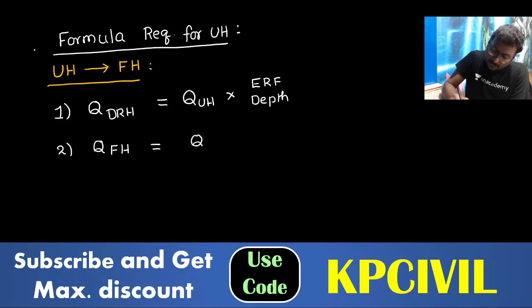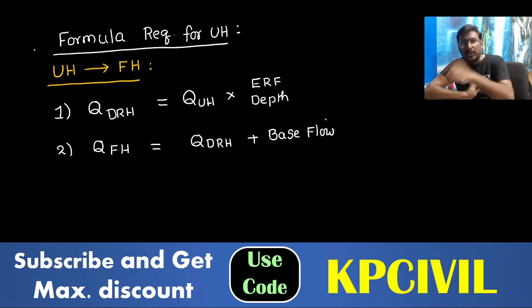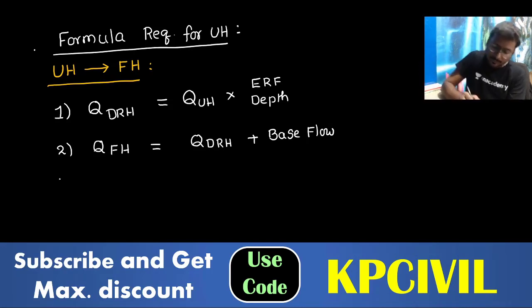QFH is equal to QDRH plus base flow. This is just the opposite of the previous construction of UH from FH. Previously we constructed UH from FH, now you are solving UH to FH. Direct runoff hydrograph discharge is equal to unit hydrograph discharge into effective rainfall depth. Flood hydrograph discharge is equal to direct runoff hydrograph plus base flow.